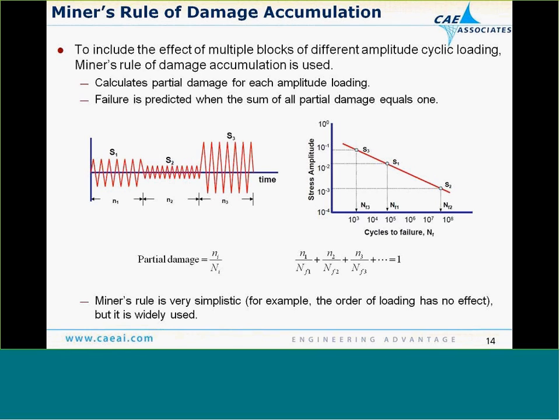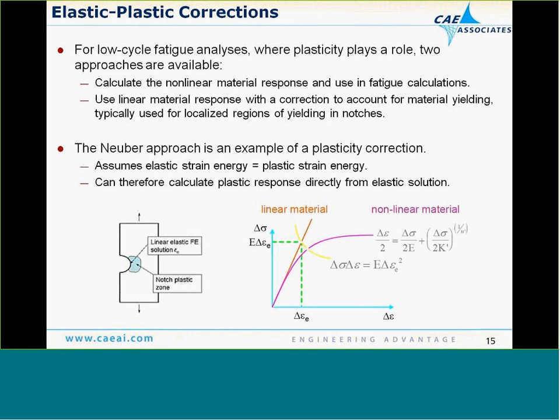This is a very simplistic approach. One thing to consider is that the order of loading has no effect at all. However, even though it's simplistic, it's still widely used in the fatigue world, and it's what nCode will do when you apply different cycles.